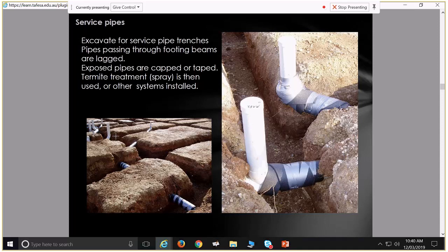So you've got a plastic membrane that goes down, and rather than just dosing the soil with stuff to kill termites, there's a thing like that which provides a plastic membrane, but it has the termite poison inside two layers of that plastic membrane. So if the termites try to eat through it, then they hit the poison. But if they're not eating through it, then it's not going into the soil. Or you've got things like this bit of Termimesh, which is pretty low tech, but yeah.